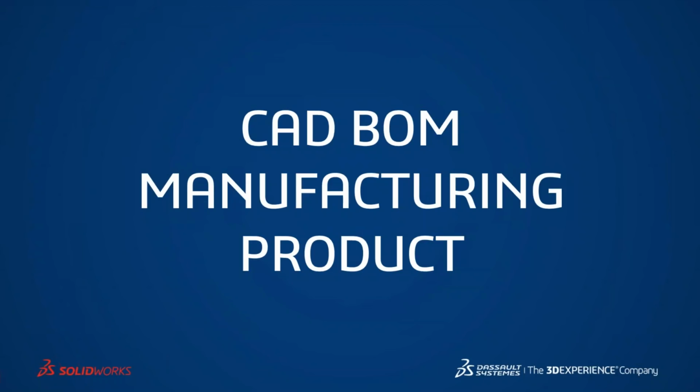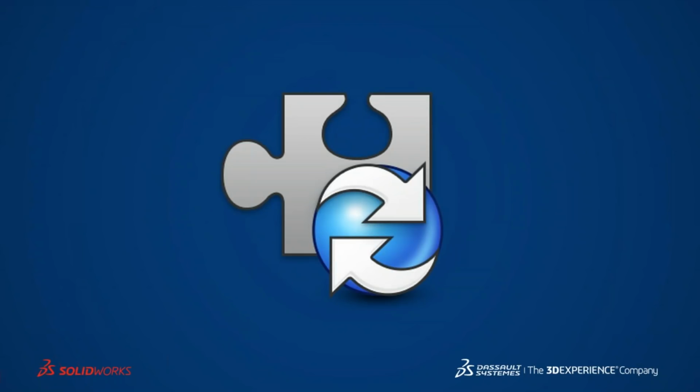There's some additional capabilities that are often needed as we extend out, as oftentimes manufacturing needs a specific bill of material that maybe includes tooling or includes additional components that we're not actually going to model. Packaging, shipping slips, etc. These might either be a manufacturing or a product bill of material, and this is where we start to look at needing some additional capabilities, needing to extend the ability of PDM into SOLIDWORKS Manage.